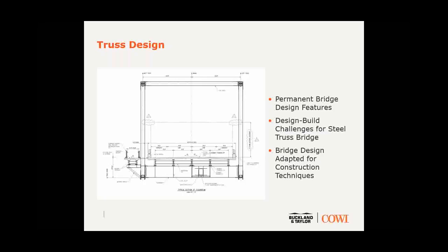Basically, the floor beams are rigidly connected to verticals, and that frame system is stronger, of course, at king posts where it passes over piers and transfers lateral forces from above down to the pier. Top and bottom lateral bracing systems, and a cast-in-place concrete deck supported on rolled stringers, which are in turn supported on welded floor beams.